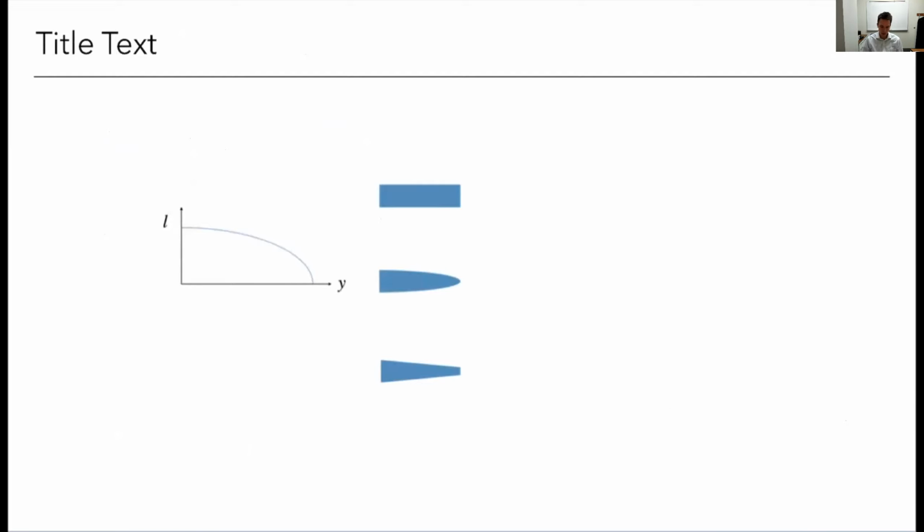So what I have on the left is a lift distribution. And this is common in an aircraft. So here's like, say, half a wing. Y is always the span-wise coordinate. So there's really another half of the wing, but by convention, almost always, these aircraft are symmetric, and so we only plot one half. So this is like half of an ellipse. If you wanted to plot the whole lift distribution, it would keep going to form an ellipse, but we generally just show half because it's going to be symmetric. And so the Y is out the wingspan, so right here would be the wing tip.